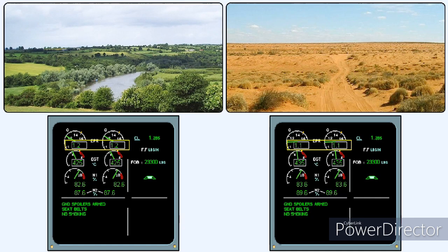We've already noted that on a hot day the air density will be lower than the international standard, and thus, as we saw from the simple form of the thrust equation, the thrust developed by an engine running at a given RPM will decrease below the level it would attain on an ISA day.